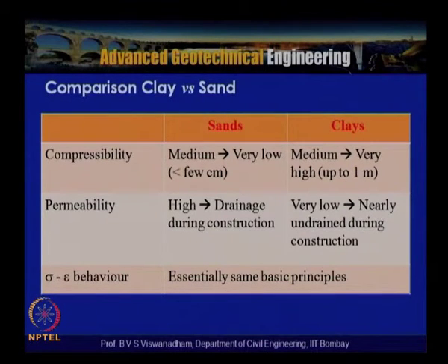The compressibility can be very high, up to 1 to 1.5 meters for certain types of clays, and it is rated as medium to very high for clays, and for sands medium to very low, sometimes less than a few centimeters.